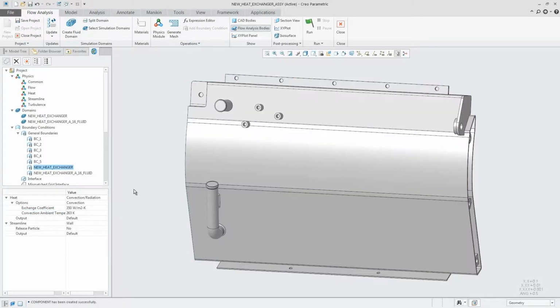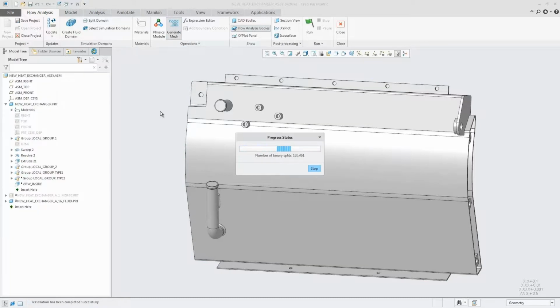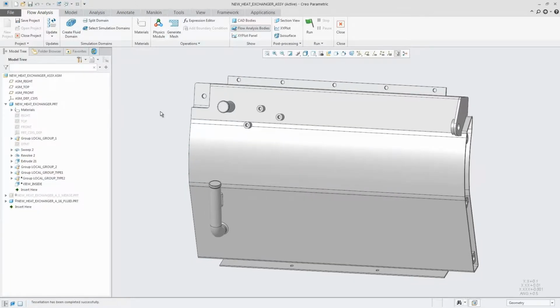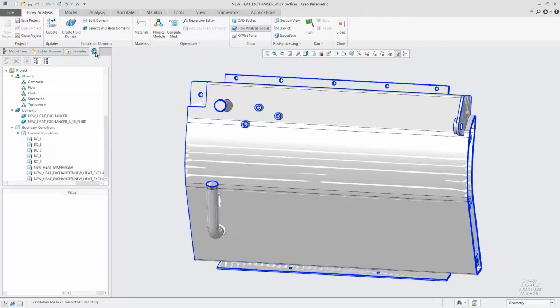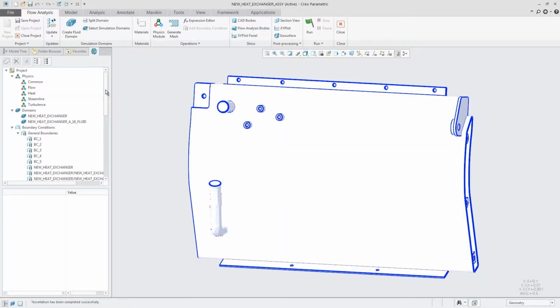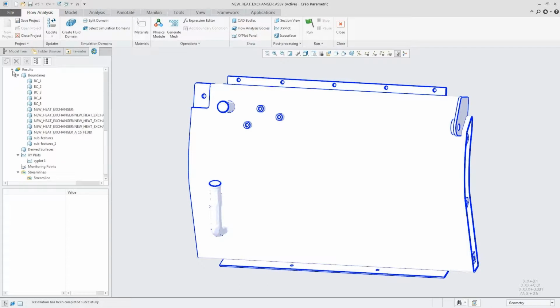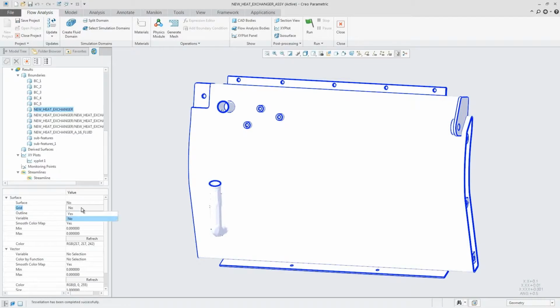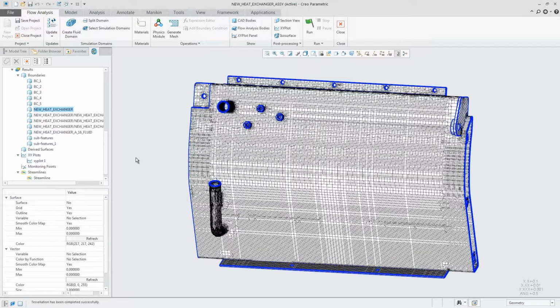And so now once we've added all this in, we can then define the mesh for the fluid flow. Again, that's not something that I need to go through and manually do. Creo actually is able to build out that mesh for our model automatically. We can simply open up that grid, make sure that everything looks how we want it to. And so observing it here, obviously any areas where we're going to have more of a flat geometry where it's not changing as much, we can spread out that mesh a bit, and anywhere that we might be seeing a little bit more complexity, a bit more curvature, we can refine the mesh there, and we have options to go through and mess with that if we need to.